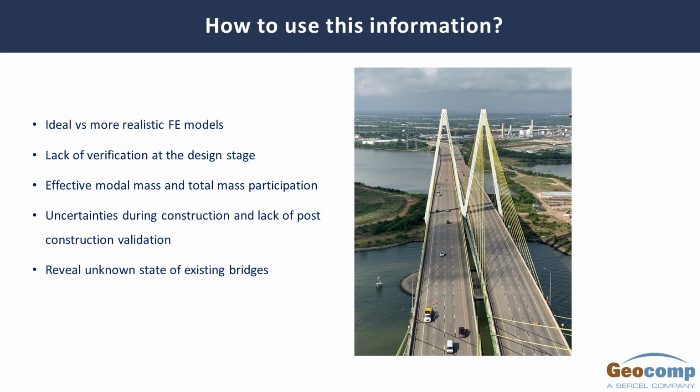Basically, coming up with a nice finite element model will drive accurate results for either static or dynamic interpretation of your loads. Right now, there's a lack of verification at the design stage. As I told you, more and more we are seeing a lot of complex bridge designs going through wind tunnel studies. So the idea is that when you create a model, through wind tunnel testing you try to understand if your model is giving the same results. Almost all the long span bridges around the world right now go through these tests, and then people get their models verified through that.